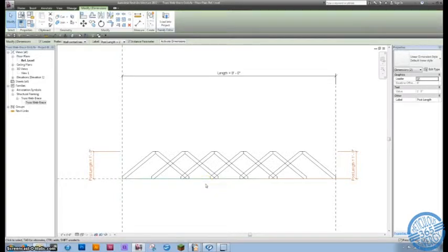This also has the added benefit that if you ever want to stair step your array, you can change one of these parameters to something else and it will step accordingly. So now we have a fully functional array that is completely responsive, and those are the steps you need in order to make that work.